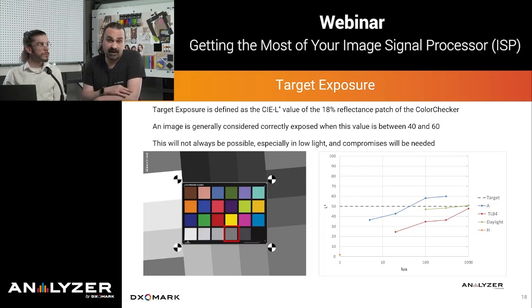That depends on a number of factors, including how big your sensor is and what your focal length is, because it influences the field of view and so forth. But generally speaking, for your camera, you're going to have an exposure time that you cannot exceed, because otherwise you get motion blur. Once you get there, you need to start increasing the gain, the ISO speed. Increasing the ISO speed, you're getting the same amount of light, you're just multiplying it by a bigger number. So yes, the average increases, but so does the noise.